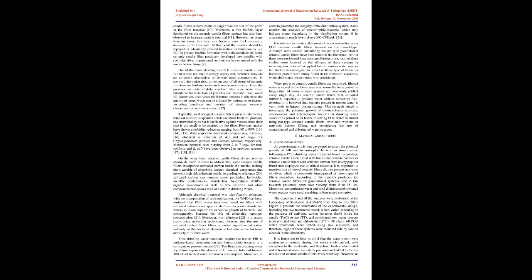17, 18, 19. On the other hand, ceramic candle filters do not remove chemicals by themselves. In order to address this, some ceramic candle filters incorporate activated carbon inside the candle, making them capable of absorbing various chemical compounds that present high risk to human health. According to reference 20, activated carbon can remove some pesticides, herbicides, metallic contaminants, disinfection byproducts (DBPs), organic compounds, as well as free chlorine and other compounds that cause taste and odor in drinking water.